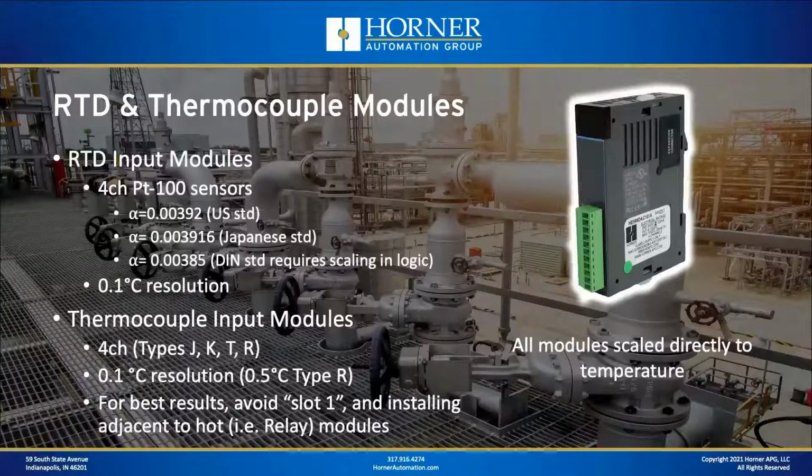Now there's also RTD and thermocouple modules available, and they've got a pretty good selection of sensor support. The RTD module is 4 channels and supports a variety of different PT100 sensors with a 10th degree Celsius resolution. The thermocouple module is also 4 channels and supports J, K, T, and R thermocouples with the same resolution level as the RTD. Now here's a hint for the thermocouple.